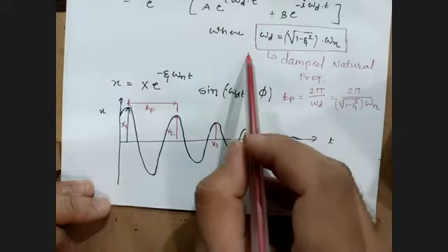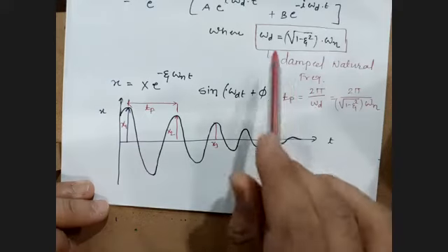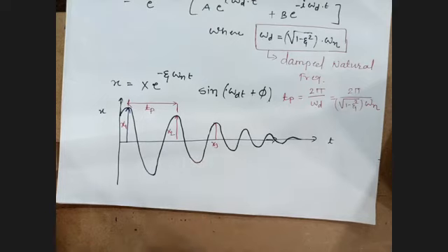So here, in the case of the underdamped system, we come up with two parameters: one is the damped natural frequency and the other is the damped time period, right? And this is your real vibratory system. Whenever we introduce any damper into any vibratory motion, which is actually used to retard the motion, there is always this kind of underdamped system in which zeta is less than 1, right? So we always prefer the underdamped system, which is used as a damper in a vibratory system.